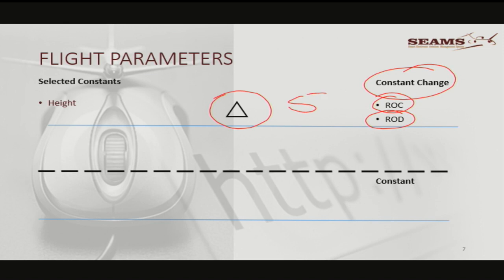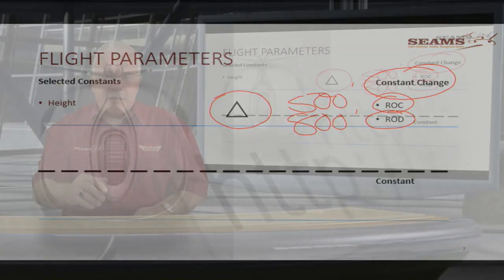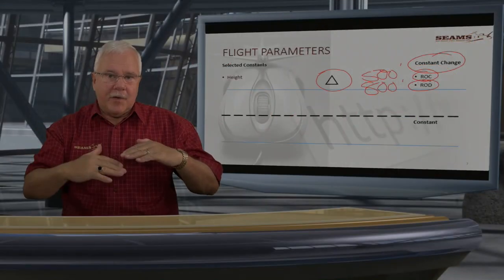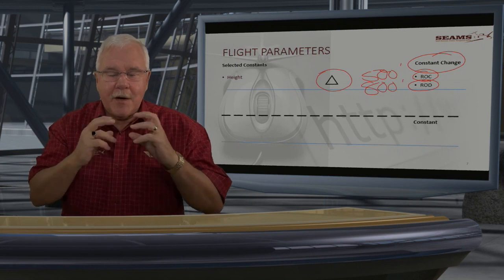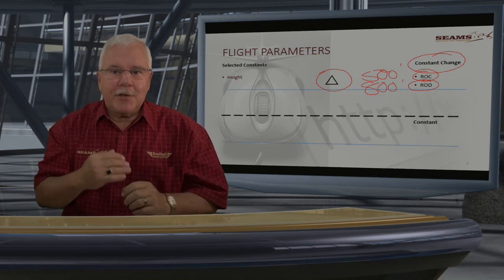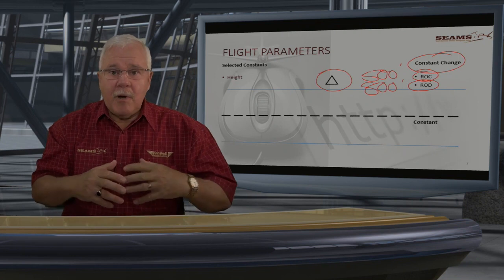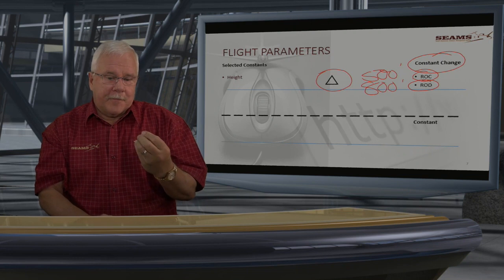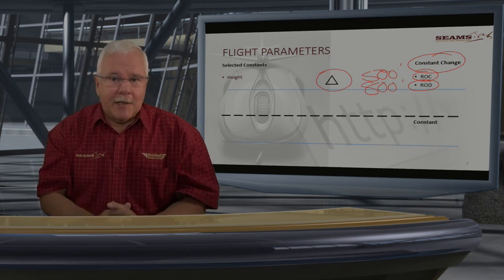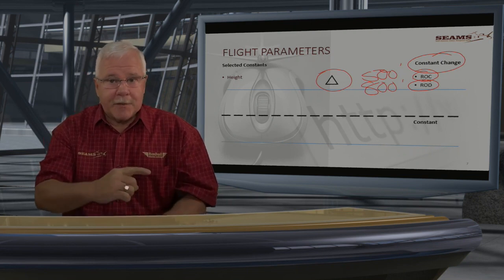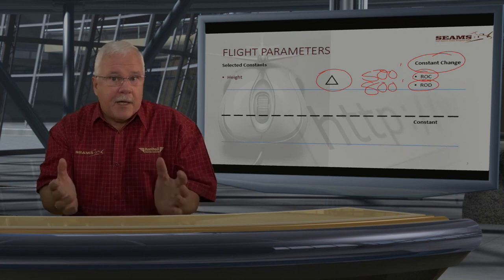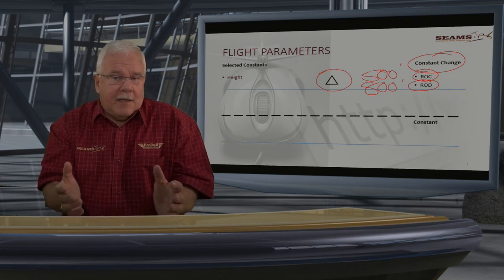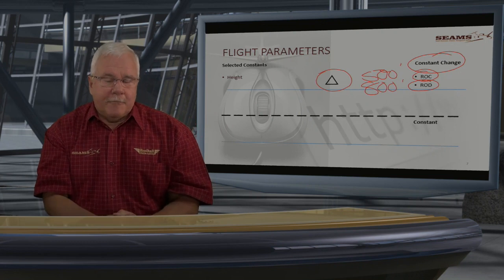We're either going to climb at 500 feet a minute or descend at 800 feet a minute, or whatever the selected rate must be. But that change, again, is not faster and slower and faster and slower. The rate of change of height needs to be a constant. Not always a selected constant, though. If I want to change the height and I just simply push the nose forward and the speed increases, then the rate of change can be, well, anything. Or I will select that.